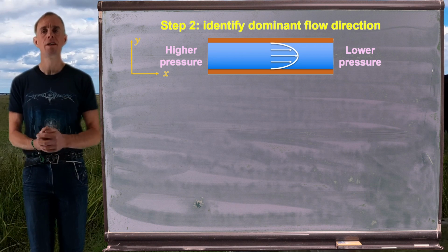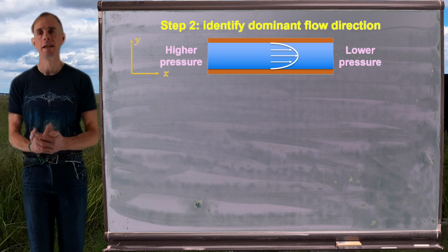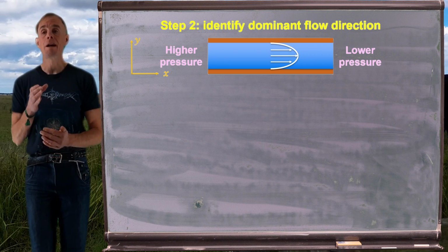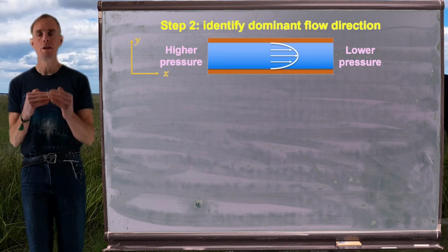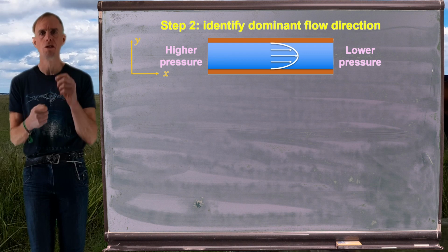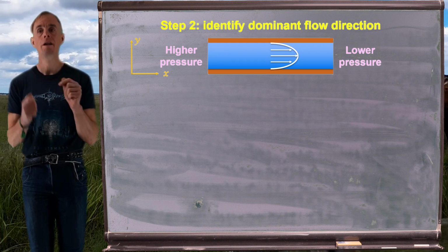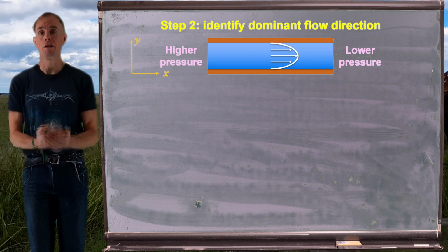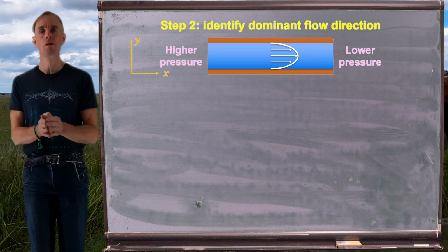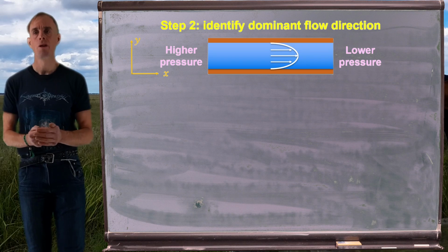The flow profile that I get for a Newtonian fluid in laminar flow is parabolic, and we'll prove this in a minute. But the parabolic flow results because the fluid at the walls doesn't move. The fluid's kind of attached to the walls, and so you've got two anchor points there. The fluid in the middle of the flow doesn't feel wall effects and moves very quickly. In fact, it moves at the maximum flow velocity for this given scenario.